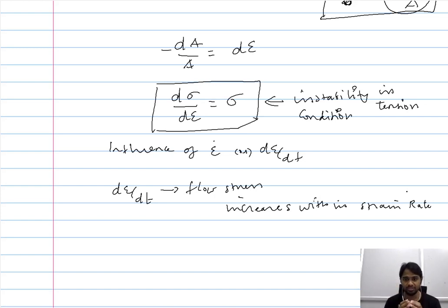When you are reducing the average movement of the dislocation, then to add to the existing plastic deformation, which is now governed by the reduced movement of the dislocation, you need to increase the amount of stress that is required. So by increasing the strain rate, you are restricting the movement of the dislocations, and therefore you need an increased flow stress to add to the existing plastic deformation.